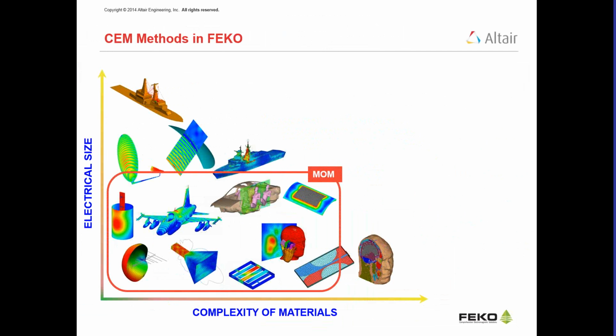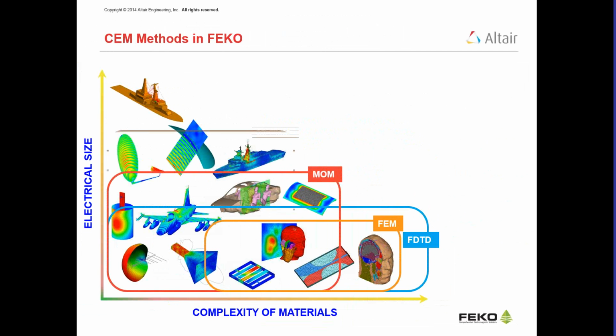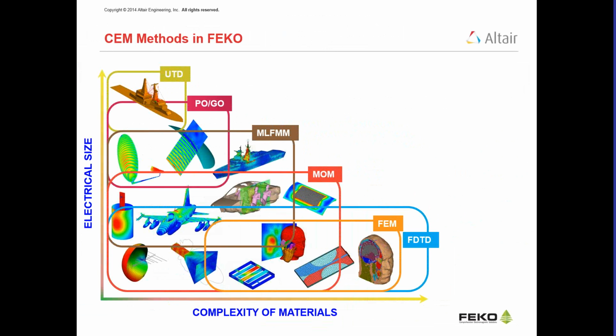One of them, the base methodology, is method of moments, and then we also have the finite element method, the finite difference time domain method, MLFMM, the multi-level fast multipole method, and physical optics, geometrical optics, and UTD. The methods FDTD, FEM, method of moments, and MLFMM can be termed full wave methods.